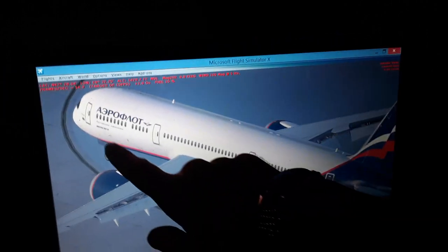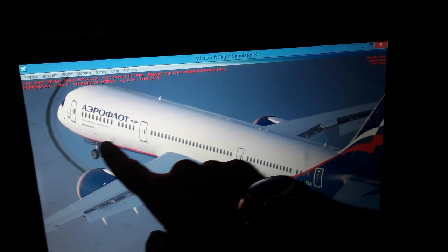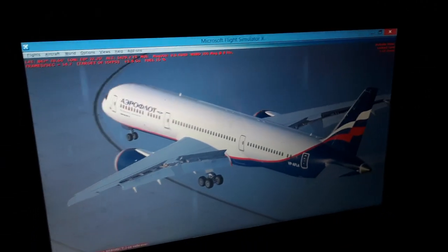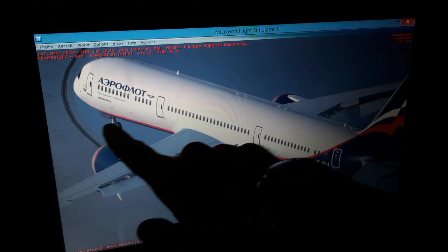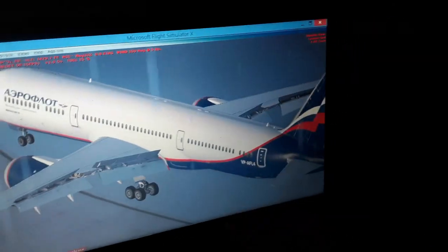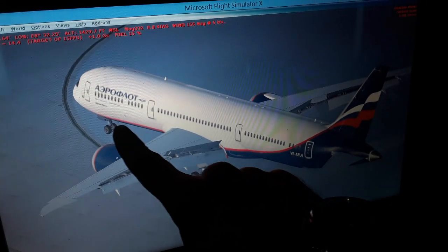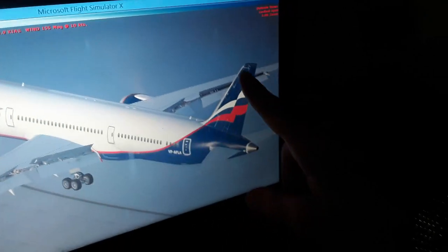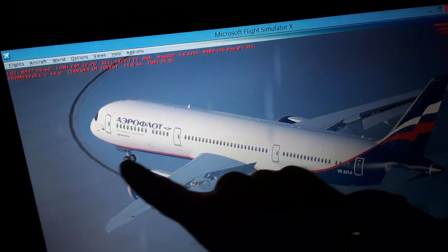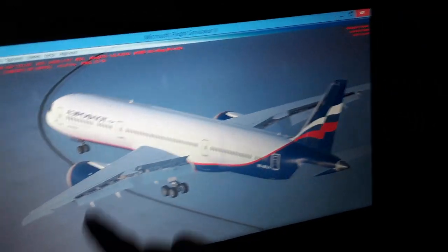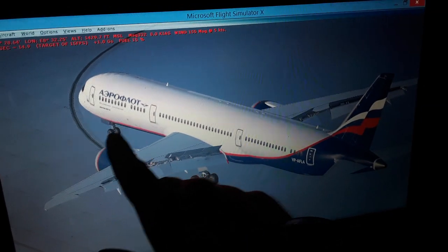You have also the nose wheel. It deflects left and right from the tiller or from the rudder pedals, like 76 degrees either side, left and right, in takeoff up to an airspeed from 0 knots to like 45 knots. Then the rudder becomes aerodynamically effective at 45 knots. Then the nose wheel deflection decreases from 76 to like 7.6 degrees either left and right side over here.